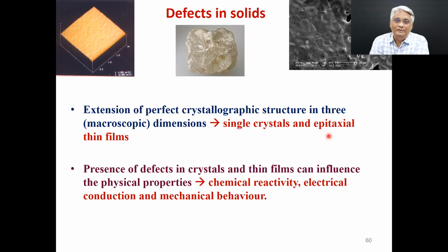That's a Greek name to describe the crystalline nature of a thin film. So you may ask me, can thin films also be in a non-epitaxial, non-crystalline form? Yes, depending on the growth processes. If the growth processes are not optimized properly, you might end up having thin films also in a polycrystalline form. But the whole purpose of growing a thin film is to get a crystalline form of the material. But it all depends on the process that you use, the parameter optimization. If those are not proper, you end up getting polycrystalline thin films. You also end up getting a non-crystalline amorphous thin film.